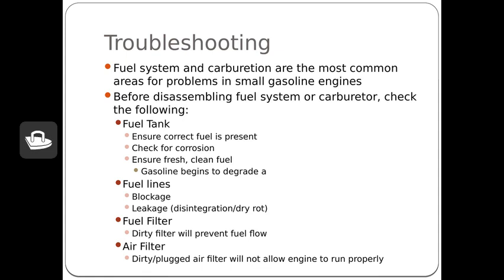So every small engine manufacturer will tell you just don't use ethanol fuel in your engine. If you're going to anyway, the best thing I can tell you to do is to run your carburetor out of fuel every time you use it. If you have a shutoff on your carburetor, like the one we looked at earlier, that's easy. You can turn the fuel off to the carburetor and run it out. That, or try to only put enough gas in to get your yard mowed or whatever. This is probably more important during long-term winter storage. If you're mowing your yard every week or every few days, you probably won't have an issue, but still, these engines are not rated for ethanol fuel.